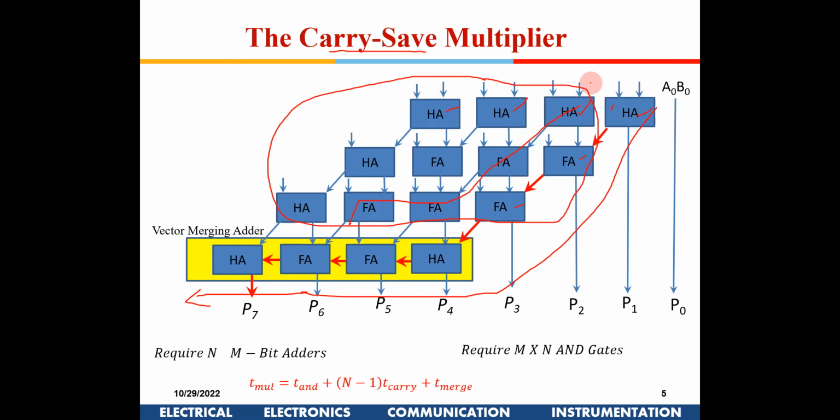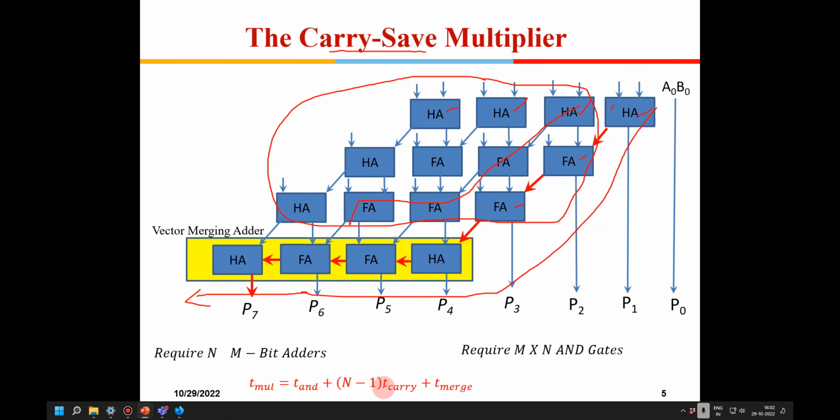So that means there is an AND gate there, plus one half adder, full adder, half adder, it is written here. So what is coming like this? These are all carries actually, which is shown at 45-degree angle, right? So 1 carry, 2 carry, 3 carry. So n minus 1 carry. Okay, so those carries are required, and this is T merge.